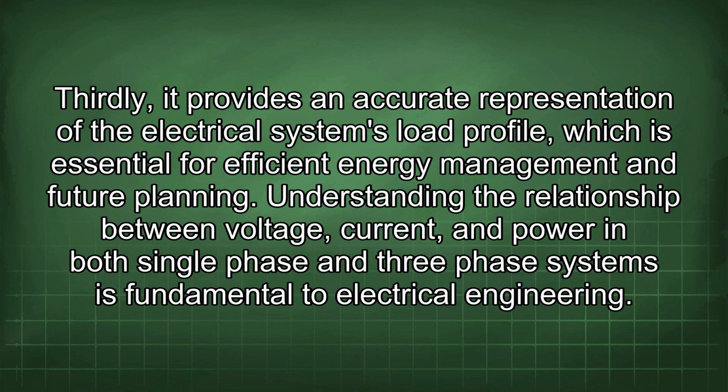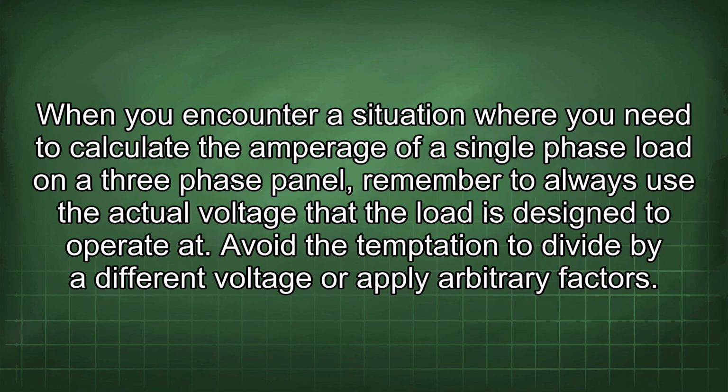Thirdly, it provides an accurate representation of the electrical system's load profile, which is essential for efficient energy management and future planning. Understanding the relationship between voltage, current, and power in both single-phase and three-phase systems is fundamental to electrical engineering. When you encounter a situation where you need to calculate the amperage of a single-phase load on a three-phase panel, remember to always use the actual voltage that the load is designed to operate at. Avoid the temptation to divide by a different voltage or apply arbitrary factors.